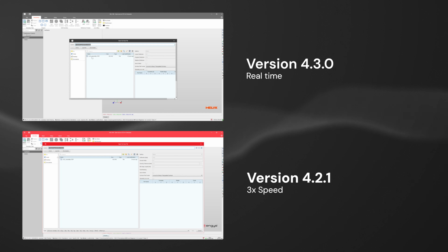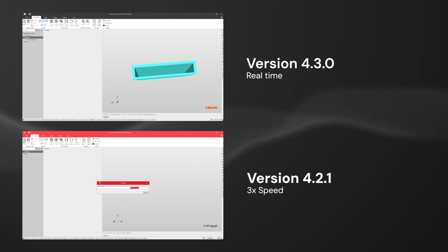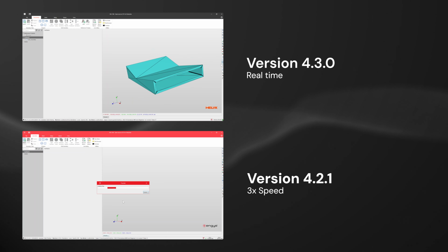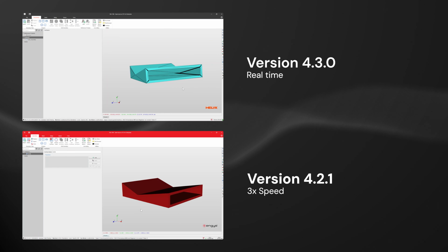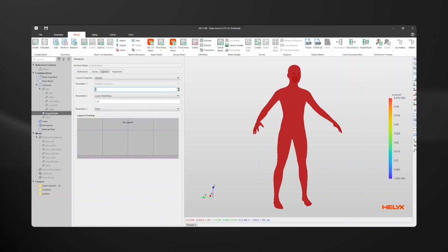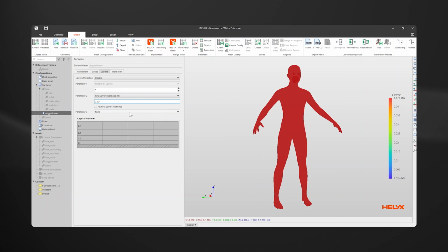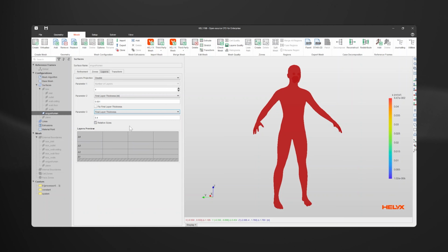Still, with respect to the Geometry tab, the CAD reader was completely refactored based on the Open Cascade library. This refactoring provides up to 100 times faster reading than the previous version, and more accurate and reliable surface representation of the original CAD file. In terms of mesh generation, we improved the interface for adding near-wall prism layers by adding the option of setting up the maximum layer thickness and final layer thickness in terms of both absolute or relative sizing, and by adding a new target expansion parameter to adjust the number of layers to match the desired growth ratio.